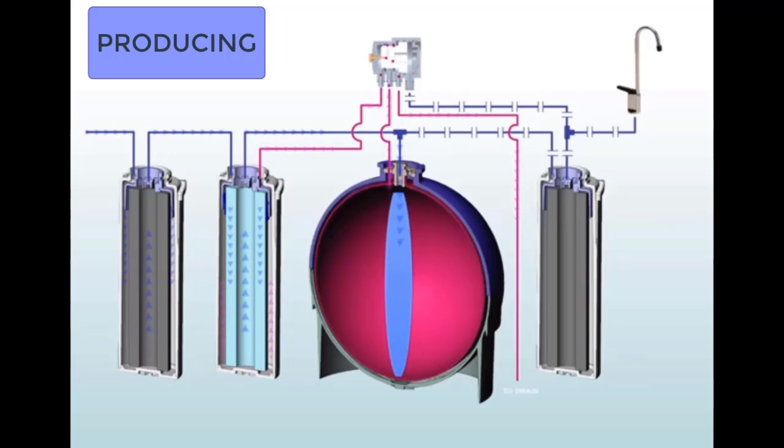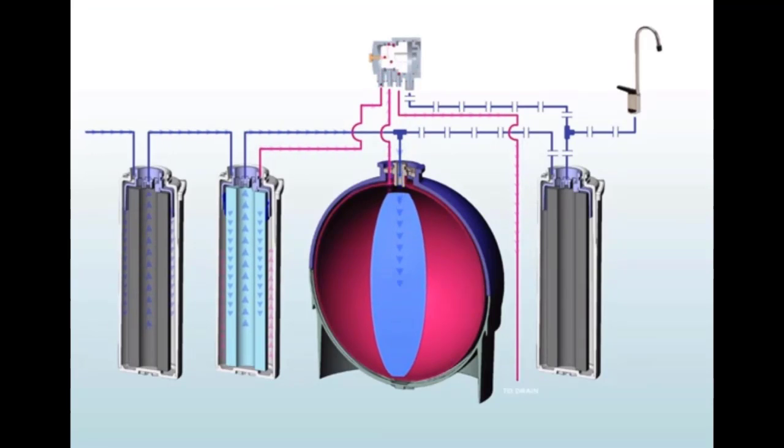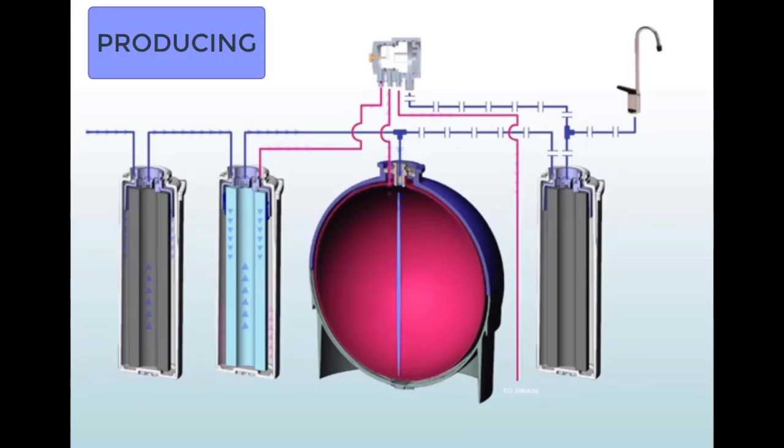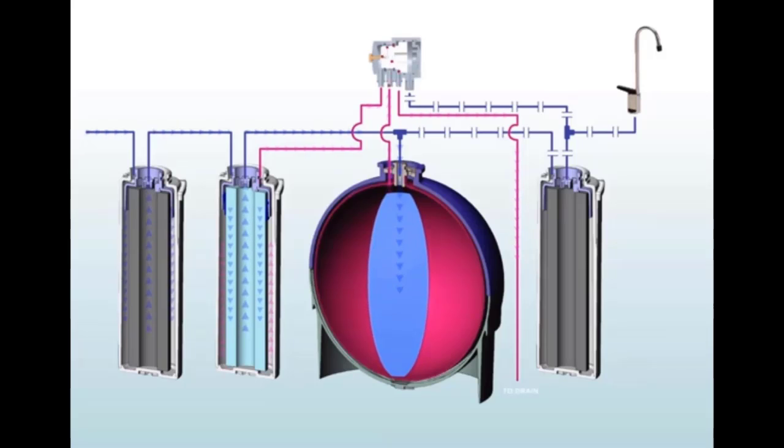There's only two factors that will affect this RO system as you look at it. One will be temperature of the water. Okay, so the temperature correction rule still applies because, again, we're talking about the effect of cold water on a membrane. And the other factor is incoming pressure. If you only have 30 psi coming into this RO system, then that's all you're going to achieve at best coming out of the faucet.